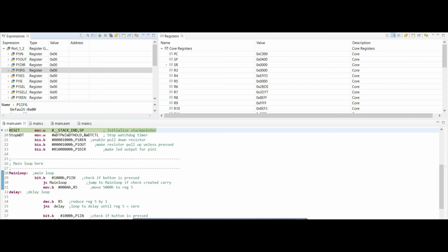Let's start with polling. Polling is a process in which a CPU constantly looks for a change in the status of a device, or polls. Until that's given, the CPU cannot continue its operation. That will slow it down because it's waiting for something to happen. When it receives the condition that was given, it will then continue on to the next program and follow from there.